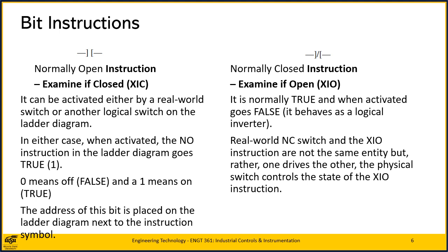Suppose you actually wired a normally closed switch to the PLC and used it to control an examine if open instruction. Then, if the real switch was activated, it would send a 0 to the PLC, and the logical XIO instruction would invert this false to a true, which may be backward from what you expected.